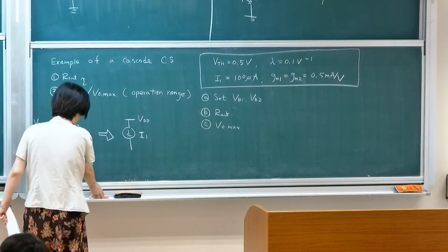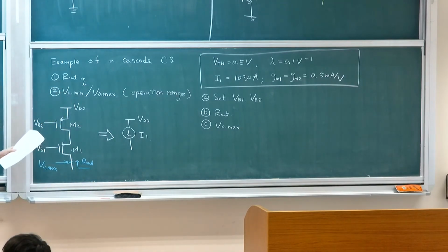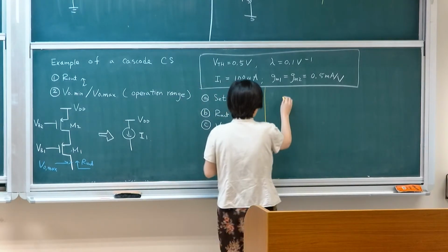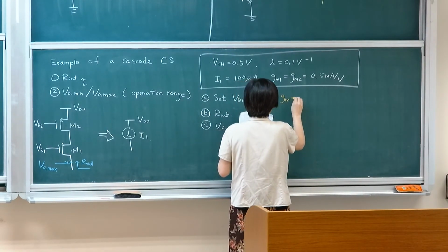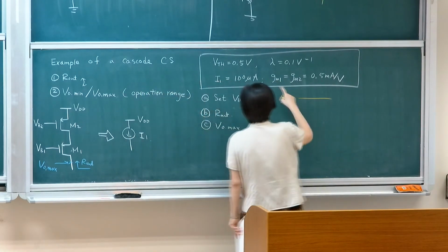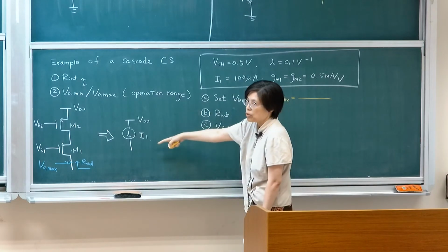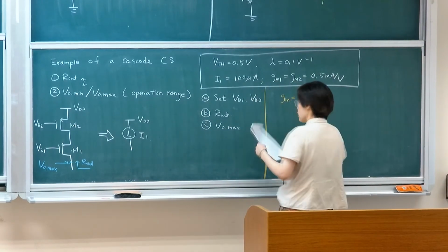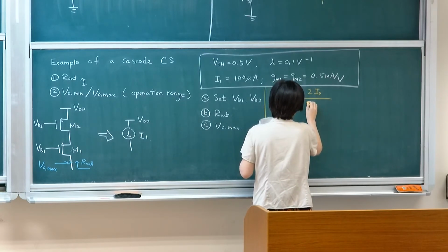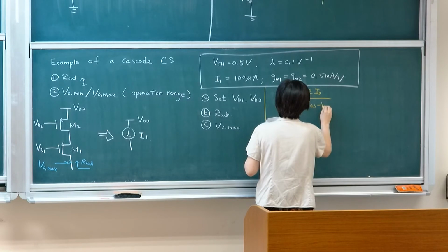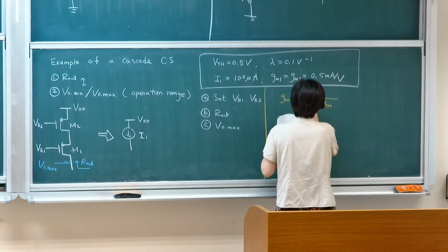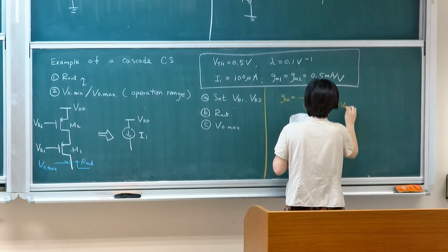So let's start by determining, we start with part A. I'm just going to use this. We know that gm can be expressed as, once again, we use this a lot, especially in design problems, because typically current is set by your target, and then you have transconductance being set. So this is gm equals ID over VGS minus VTH, that's my overdrive, VOV.